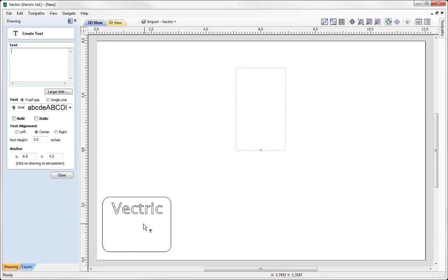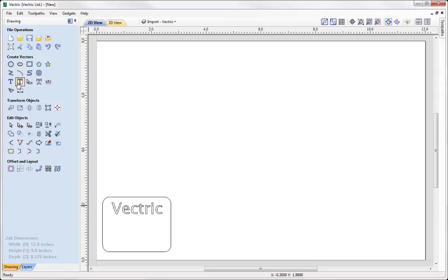However, there is an easier option, and that is to use the Draw Text within a vector box option. And so the reason that this would be better to use in this instance is that whatever the text being applied, regardless of how long the character string is, it will always fit within the required area.